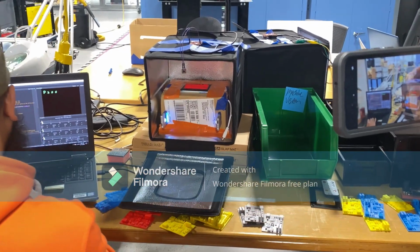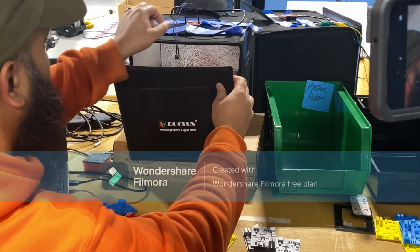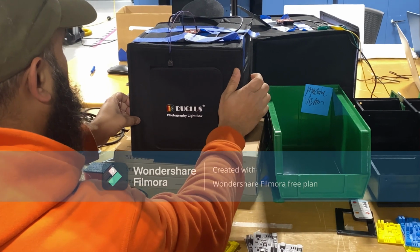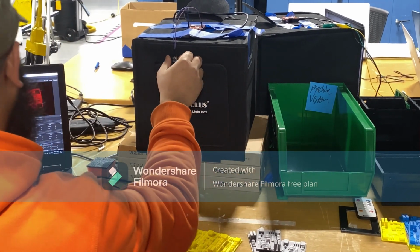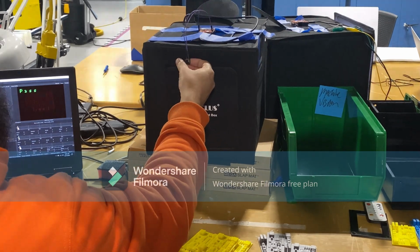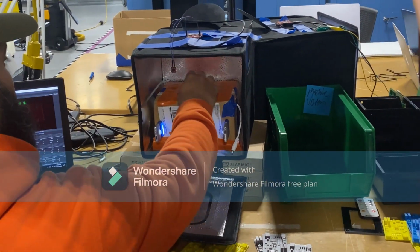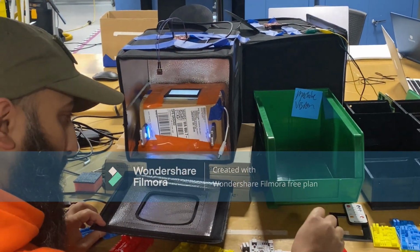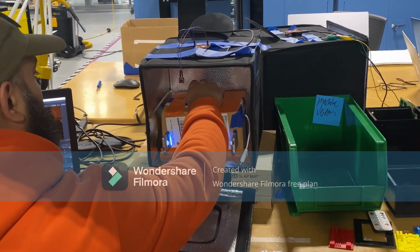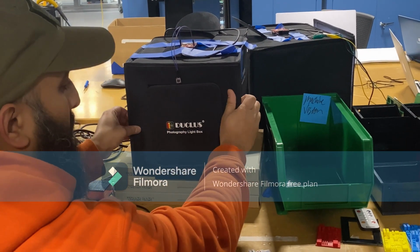In this video, you can see my classmate Sam operating the machine vision system. Both the future system and the current system are in batch flows, and this would operate on the same principle. The future system does have very close tolerances, with only a shift of 5% or more in the part causing an error, due to the technique of basic frame differencing, which saves an image and overlays the current snapshot over the image and compares their difference by a percentage, being the solution chosen.